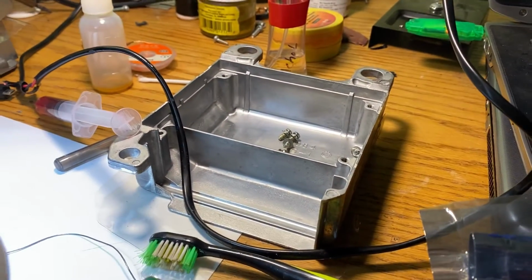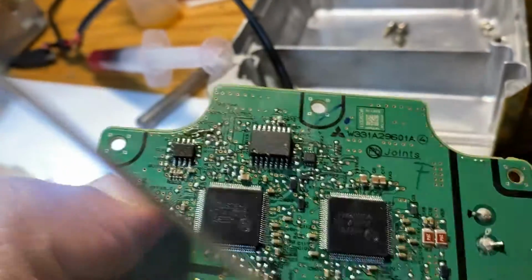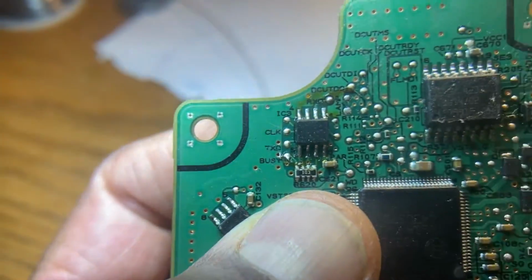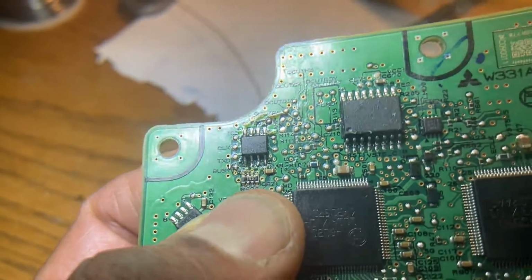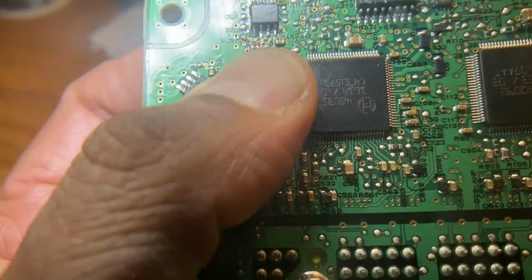When you have this fault, it reads the airbag and the read error fails. That means the EEPROM, which we fix, or sometimes gets damaged when you use the heat gun from a previous repair, is not good. This one is 95640, as you can see right here.